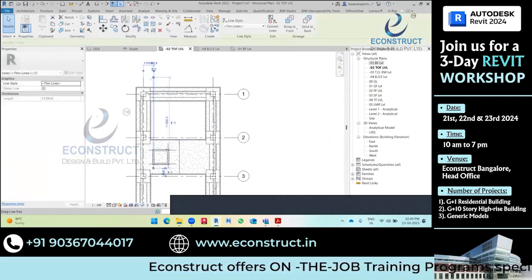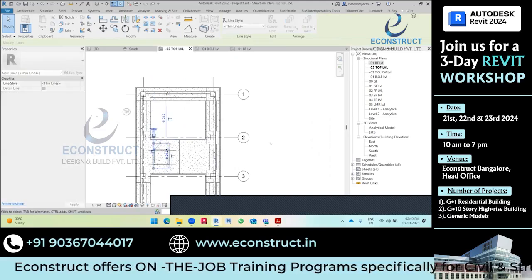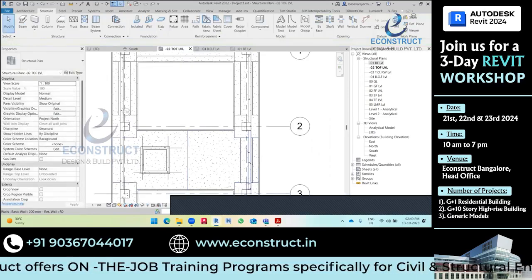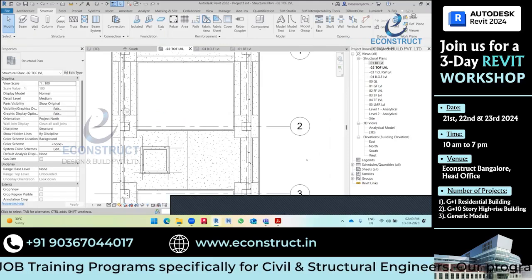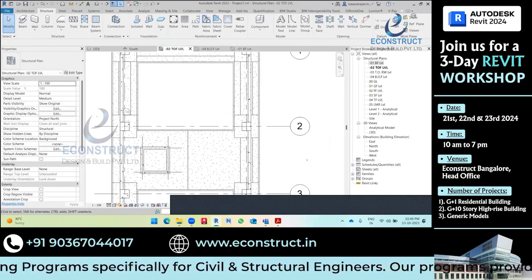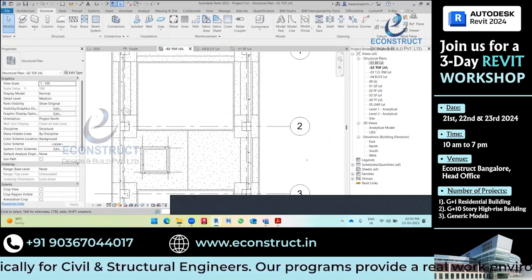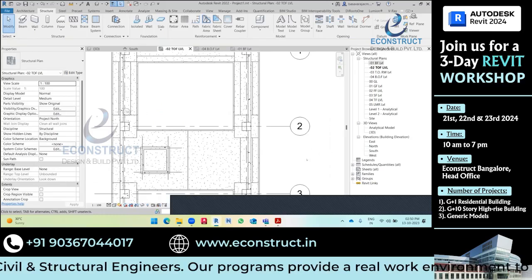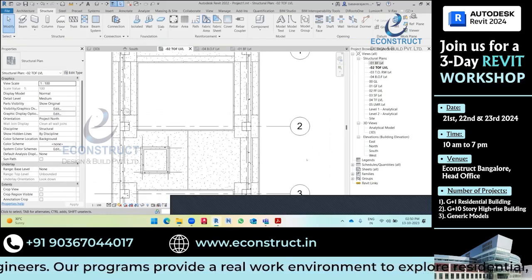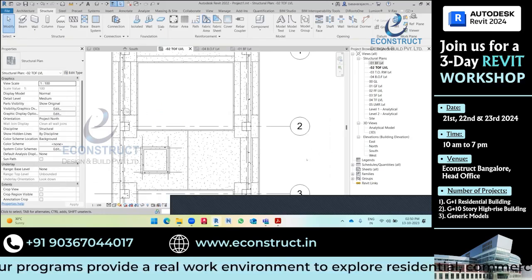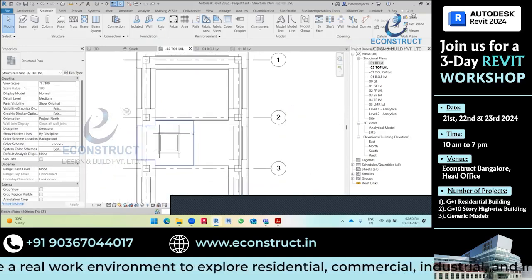Will these detail lines still be there after the model is done? Does it not make the model heavier? No, it is very light. It is only for annotation, sir. It is not a model line. There is a model line also in Revit, and a detail line is also there. Detail line is only for annotation. Model line is an element.